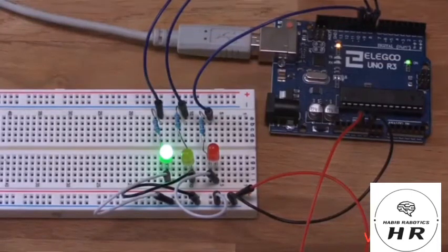Now that the code's uploaded, you should see your traffic light work, i.e. it begins on green, and then after a pause it will change to red, and then go back to green again. And since we set up that delay in our loop function, it will do this every 15 seconds forever, as long as it is plugged in. If it didn't work for you, make sure that you had the right communication port and board type set up in the Arduino IDE. Now let's move on to something a little bit more complicated.